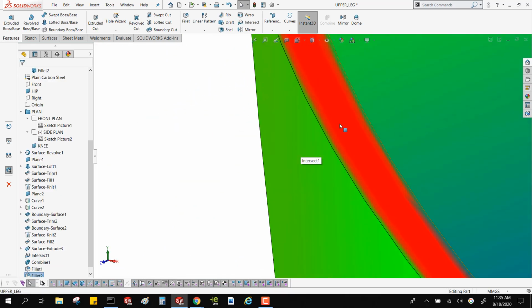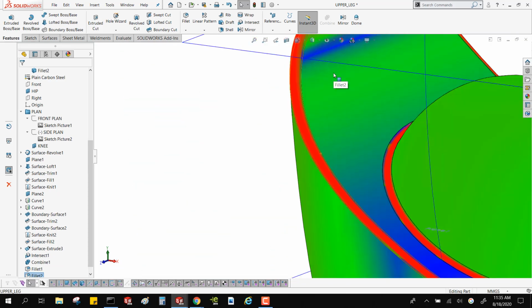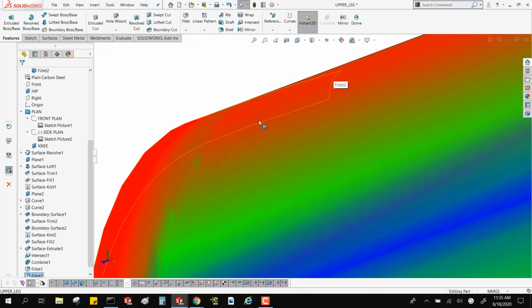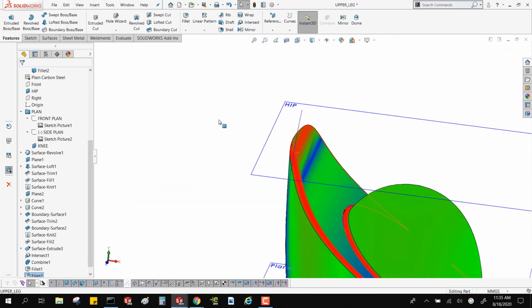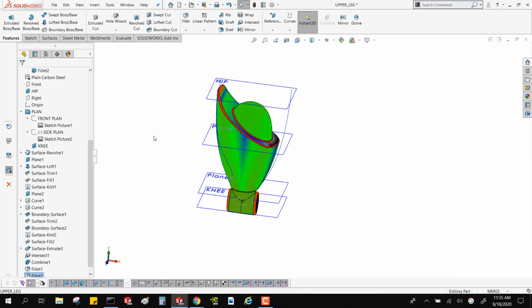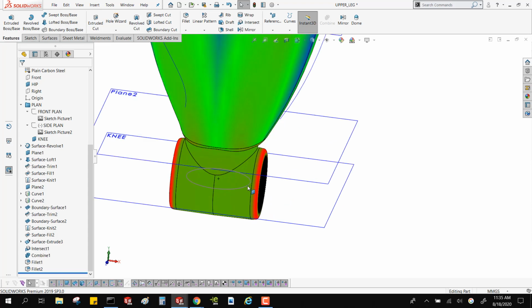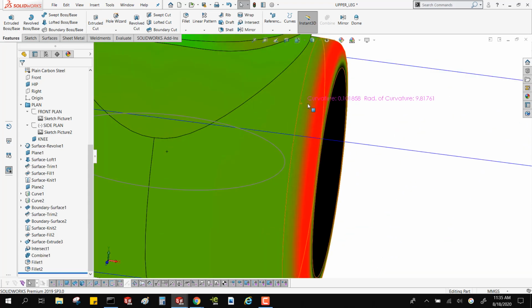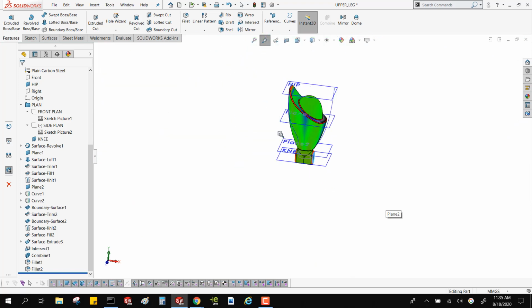So you'll see that it tries its best. It did do some of that graduation in here, but it didn't do a great job up here, just because the corner's so tight anyways. So some of that you may have to do yourself, but they do give you a good job. This is really what you're trying to get, where it's a very gradual, then a curve, and then very gradual out of it. And again, that was done using that G3 trick in the sketch.